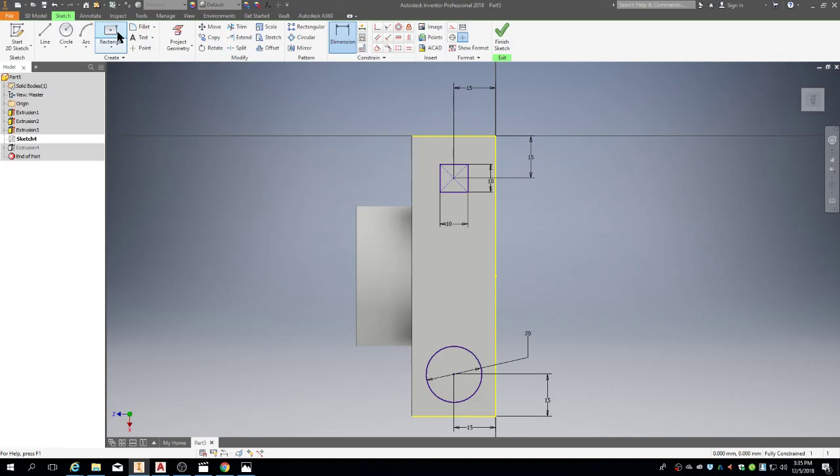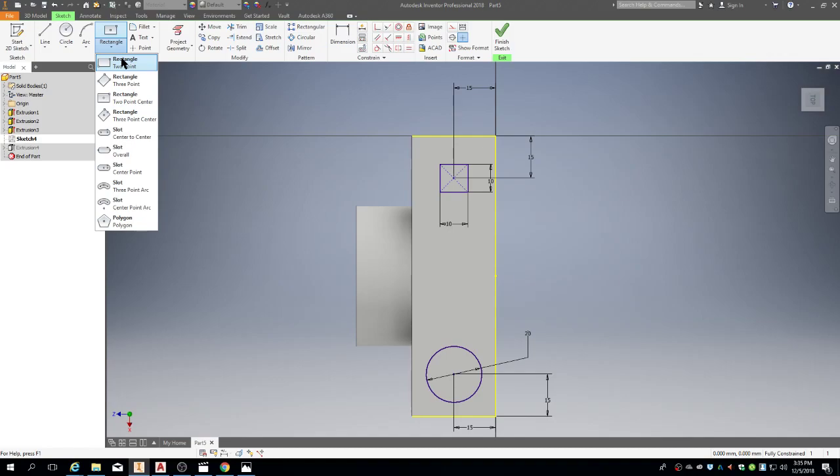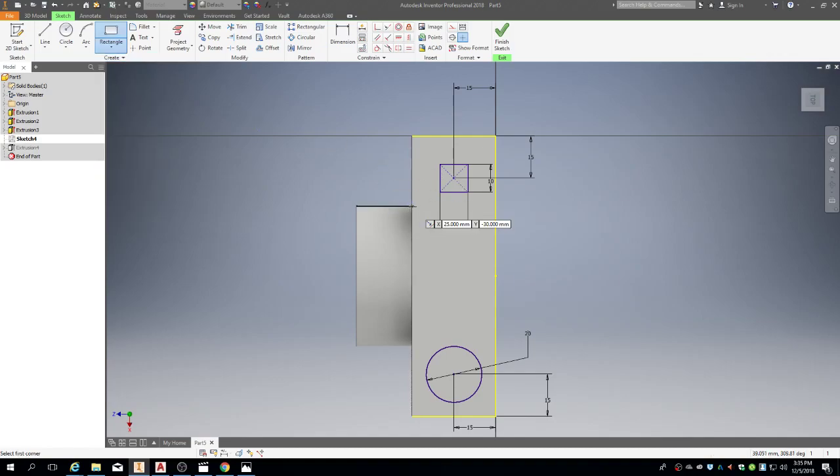While we're here, I'm going to draw the rectangle starting anywhere up here, and we can place it differently. Instead of that type of rectangle though, I'm going to go to my 2-point rectangle, start it here, drag it down, and touch on the other side. Escape that command by hitting escape.